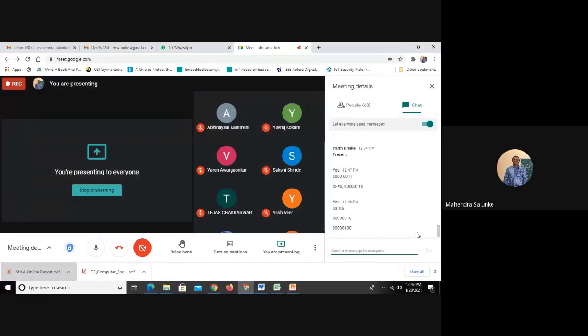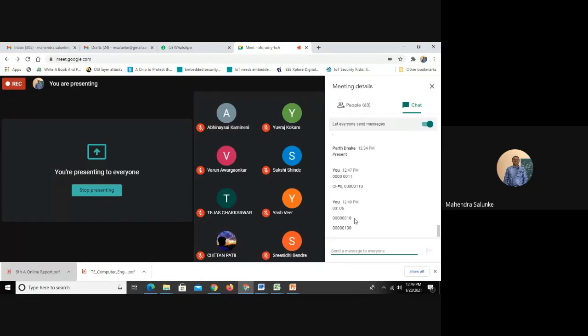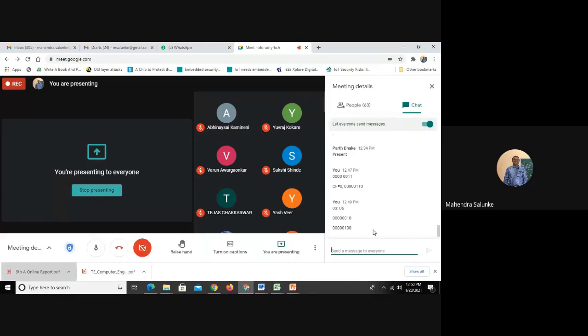So for basic division, if you want to simply divide a particular number by 2, you can shift it towards the right side. Mainly it is a shift operation. So if you are shifting towards the right side, what will happen? It is a divide by 2. There are a few examples where we will need this particular instruction, where we want to divide and multiply by 2. So you can just make note of it.